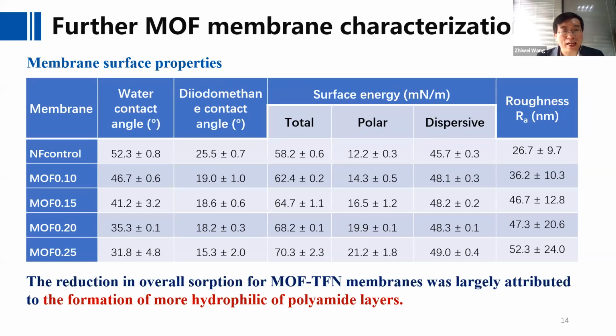Then we further validated our hypothesis. We detected the water contact angle here. You can see that for the control, the water contact angle was about 52 degrees, and after incorporation of the MOF particles, the water contact angle of the membranes decreased gradually from 52 to 31.8 degrees. It clearly showed that the incorporation of the MOF particles could increase the hydrophilicity of the polyamide membrane.